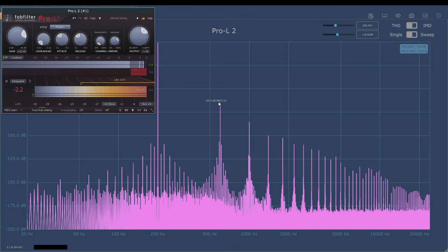First of all, transparent is a rather complex and subjective criteria and definitely doesn't equate to a simple measurement of how much distortion is added. When brick wall limiting, the trade-off is essentially between distortion and pumping, and the former will often be subjectively more transparent than the latter, especially if most of that distortion happens very briefly just after a transient.